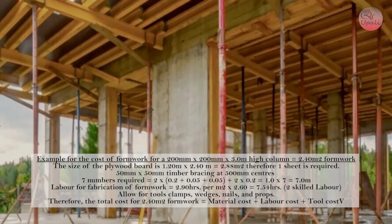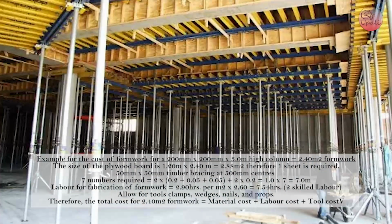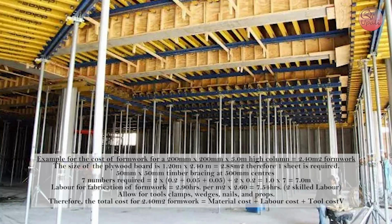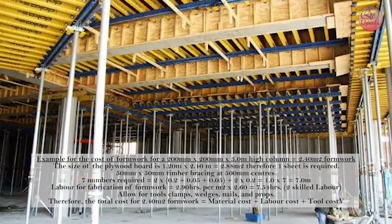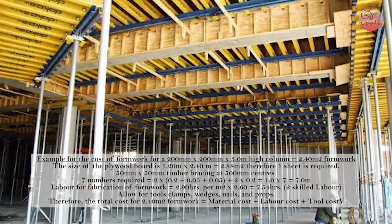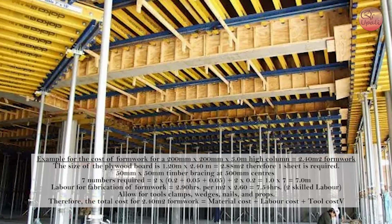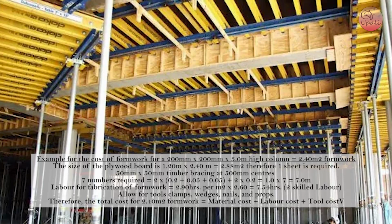The size of the plywood board is 1.2 meter by 2.4 meter equals 2.88 meter squares. Therefore, one sheet is required. 50 mm by 50 mm timber bracing at 500 mm centers, 7 numbers required equals 2 into 0.2 plus 0.05 plus 0.05 plus 2 into 0.2 equals 1 into 7 equals 7 meters.